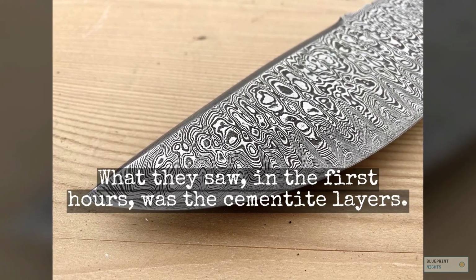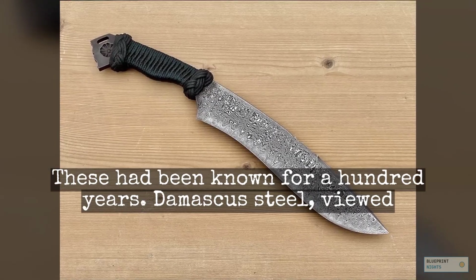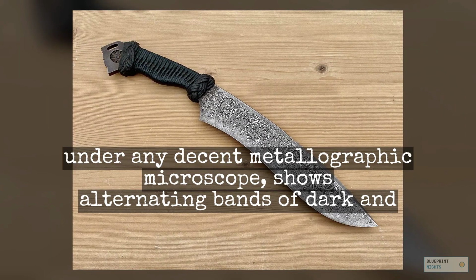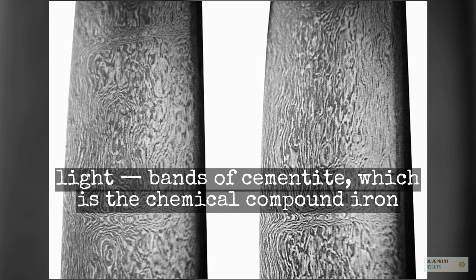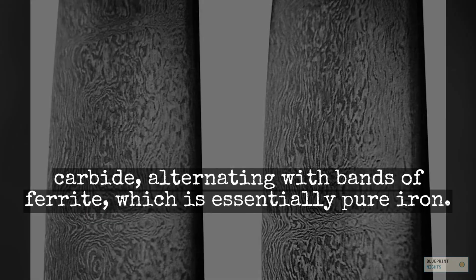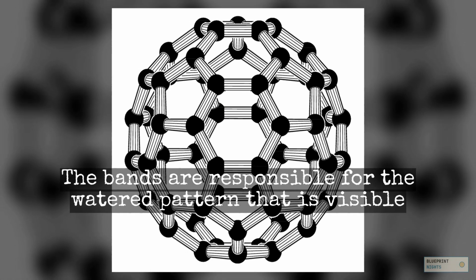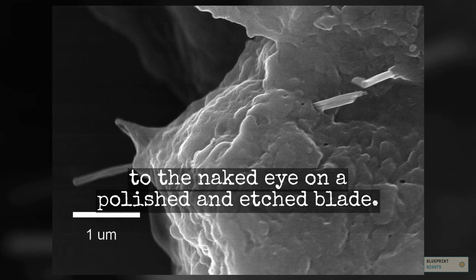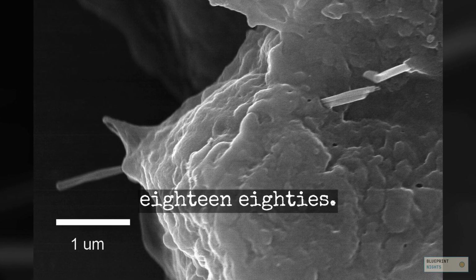What they saw in the first hours was the cementite layers. These have been known for 100 years. Damascus steel, viewed under any decent metallographic microscope, shows alternating bands of dark and light. Bands of cementite, which is the chemical compound iron carbide, alternating with bands of ferrite, which is essentially pure iron. The bands are responsible for the watered pattern that is visible to the naked eye on a polished and etched blade. This was not the finding. This had been known since the 1880s.